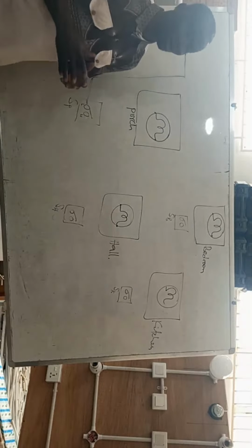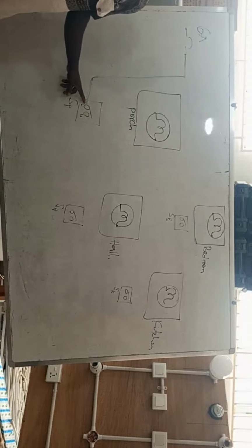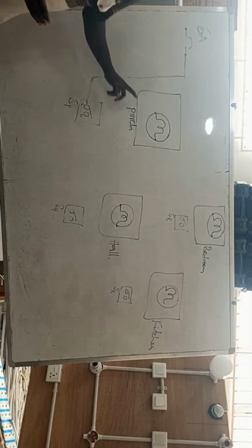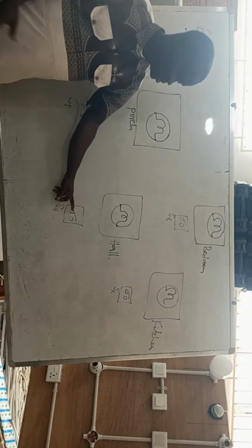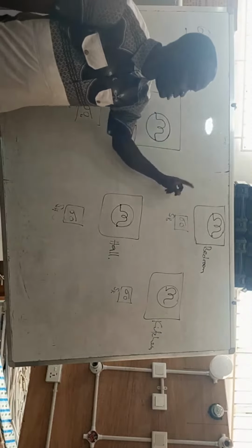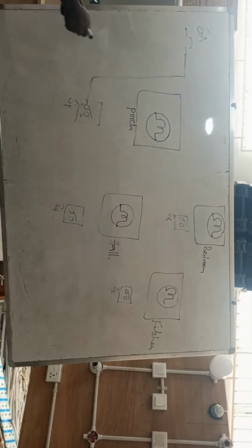In order to economize the wires, you can take a loop from the connection you made to this lamp, to this switch, to the next one, and then you take another loop to the next one, another loop to the last one. Okay, so this is how it's going to be like.